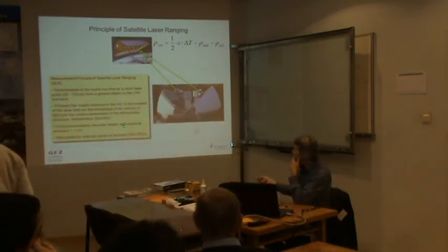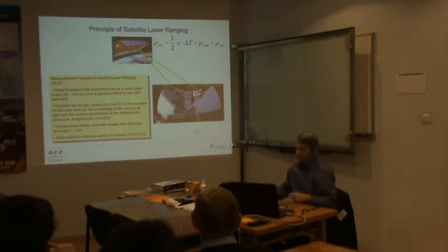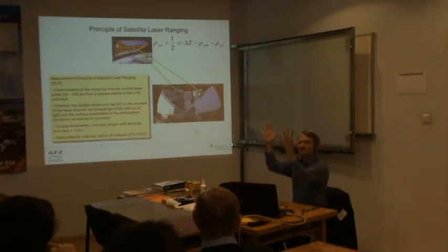Yeah, why is it absolute? The absoluteness comes from the fact that we use only a single clock. In GPS, this is something sometimes forgotten, you do nothing else than comparing clocks. You transmit a pattern of navigational signals at a given time and replicate them on ground, and shift the clock of your receiver on ground as long as you have coincidence of those patterns, and compare: at that moment of space transmitting time the signal was sent, and at that moment of ground receiving time it was received.